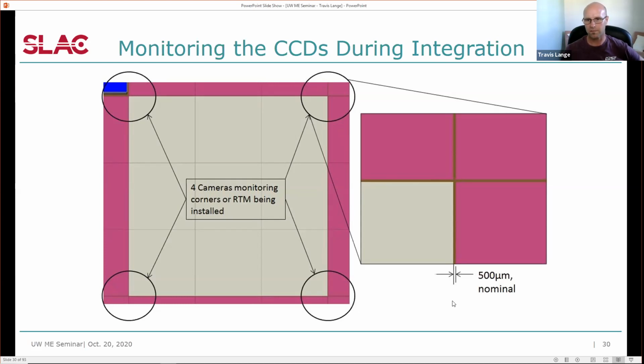And we came up with some software where we actually had a region of interest here and here, and in that region of interest, we made a series of vertical lines or horizontal lines, and then measured the relative light intensity that the camera sees. And when you do that, you can actually detect where the edge of that sensor is using the software. So that's actually one of the systems that we had to come up with in order to be able to monitor what we were seeing.